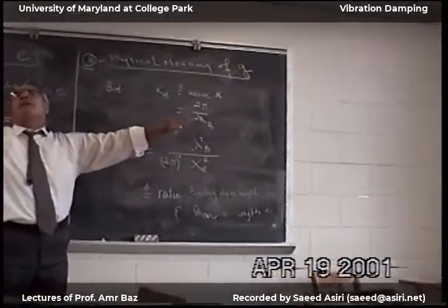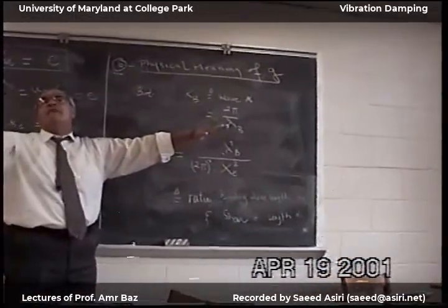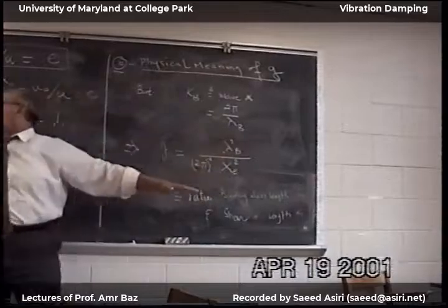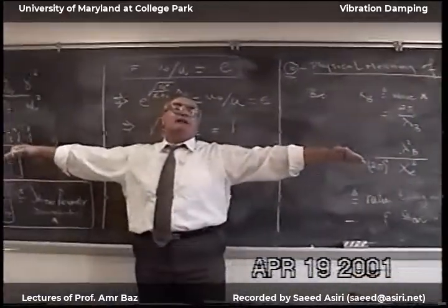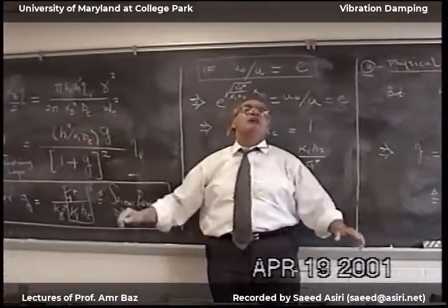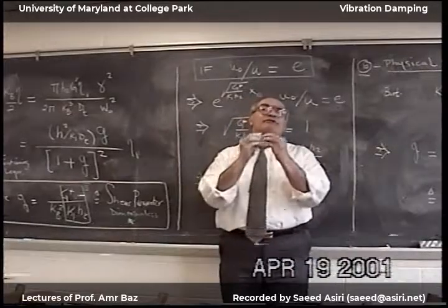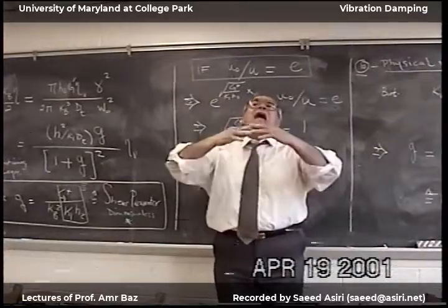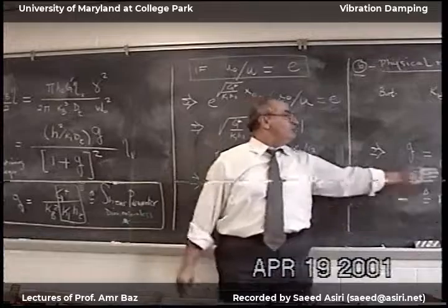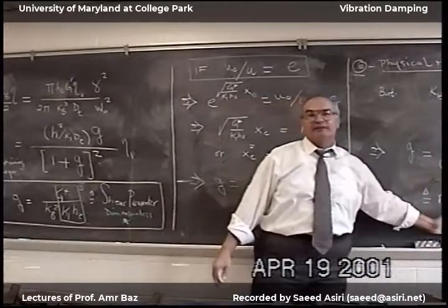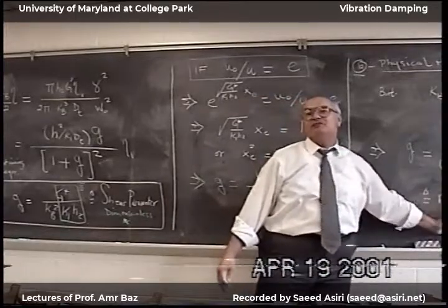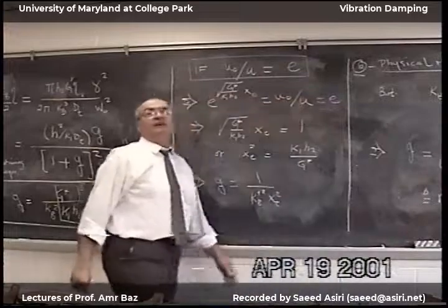If you are far from here and here, you will not have damping effectively because we will be way off at the ends of these two curves. Bottom line of all this, for constraining layer to work, we have to have balance between bending and shear. We have to have balance between these two numbers.